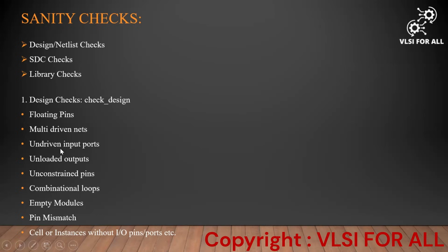The next one is undriven input ports. In our design, we have input ports and output ports as well. Whatever input ports we have in our design should drive some load at least. If not, the logic given to that input port won't be propagated to the cells connected in the design.